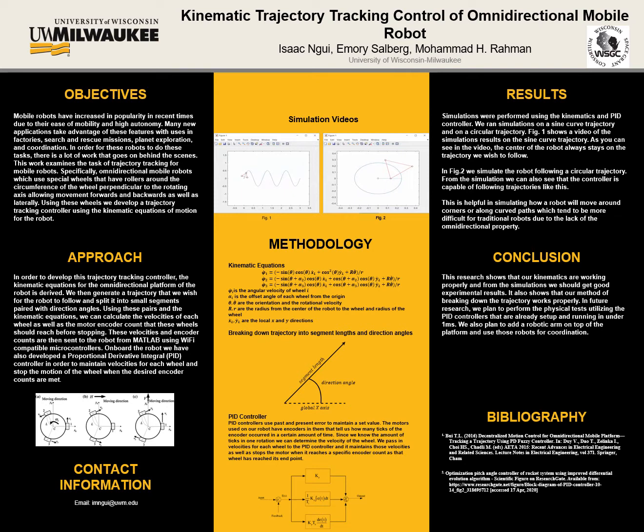So if we wanted to have a motor maintain a certain speed, let's say 60 miles per hour, a good analogy for a PID controller is like cruise control on your car. So let's say you want your car to go 60 miles per hour and it's only going at 55. What will happen is there will be error that gets passed in. So it's what you're currently moving at versus what you're desiring. So let's say our car was only moving 55, we wanted it to be 60, our error would be -5.